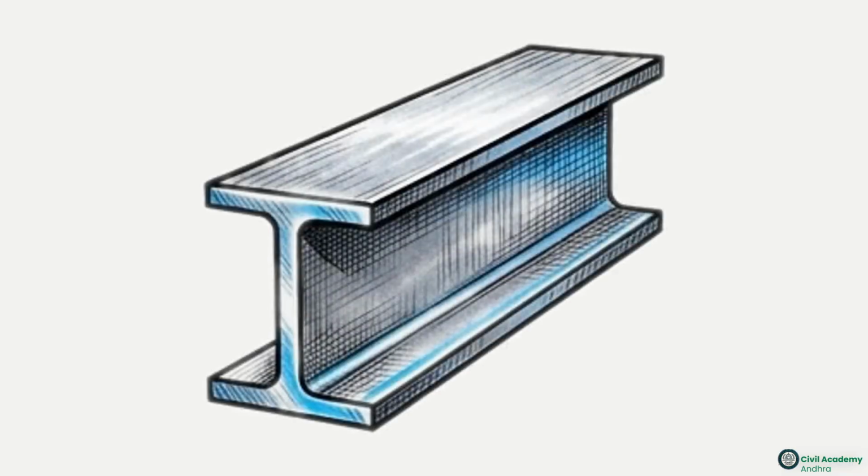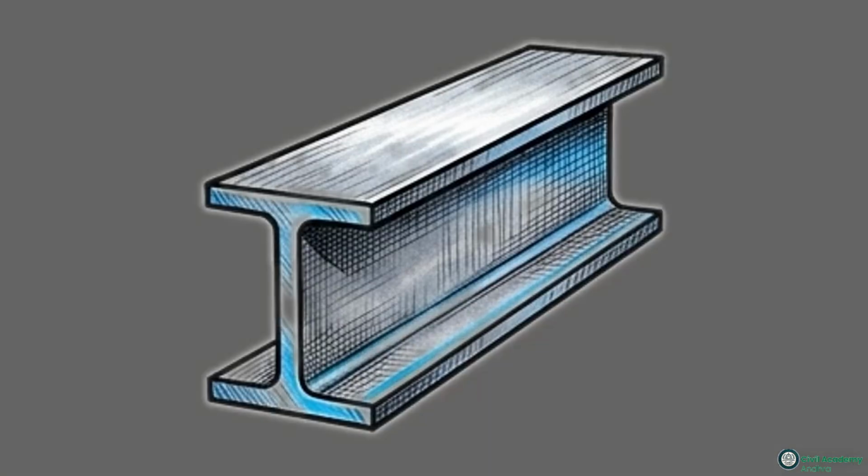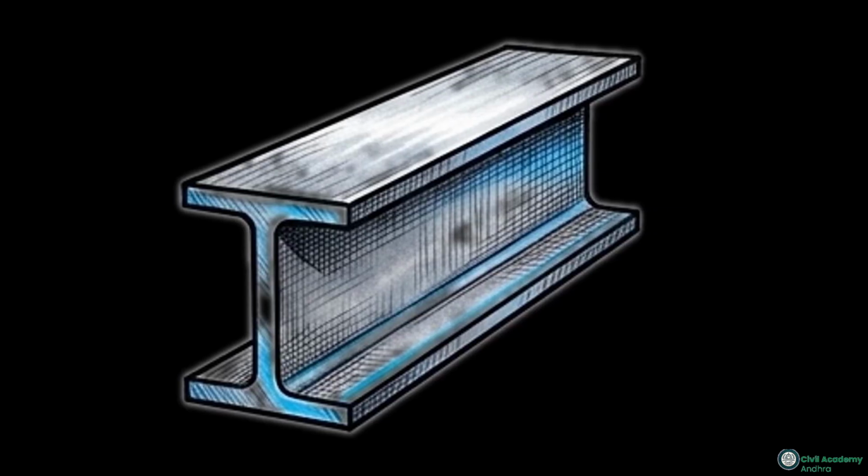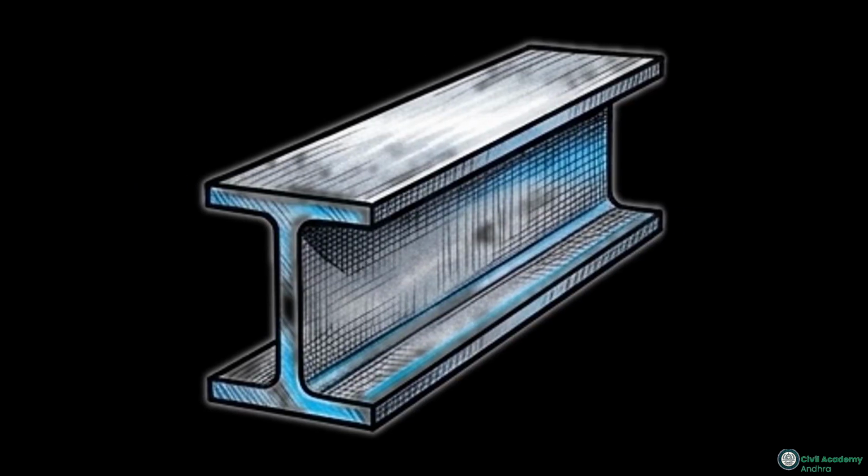We analyze these systems using a free body diagram. By isolating the object from its surroundings, we can focus exclusively on the forces acting upon it: applied loads, the self-weight pulling down from the center of gravity, and the reaction forces at the supports. The arrows we draw depend entirely on physical constraints. If a support prevents movement in a specific direction, it generates a reaction force arrow in that exact direction.